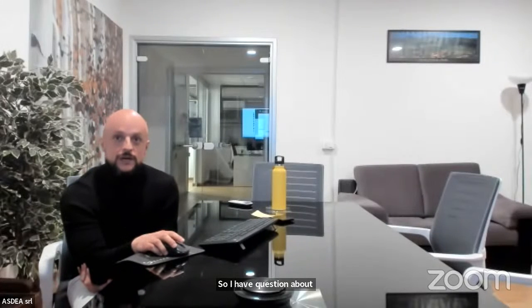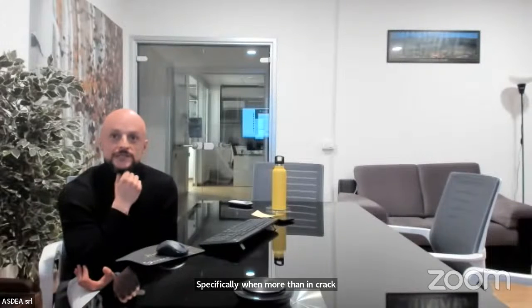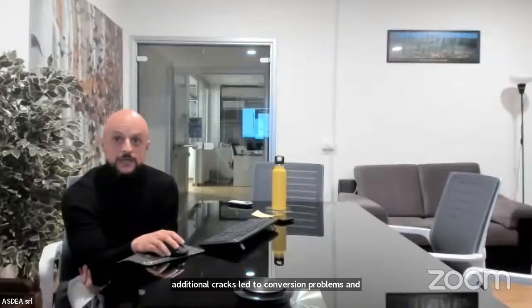Okay, then next question by Bibar Khan. You showed an XFEM model in your initial slides, so I have a question about XFEM. During my research on reinforced masonry structure, I encountered an issue with the XFEM model, specifically when modeling crack propagation. The presence of a single element with a crack followed by additional cracks led to convergence problems and ultimately caused the job to be aborted.